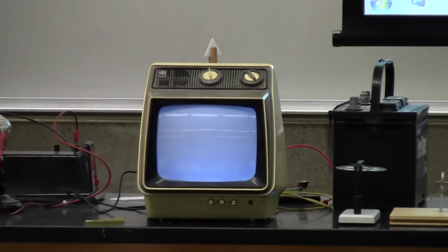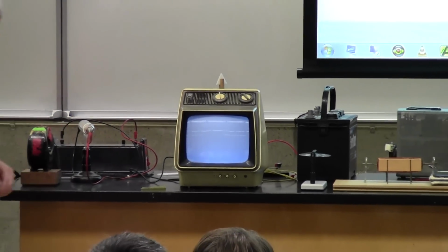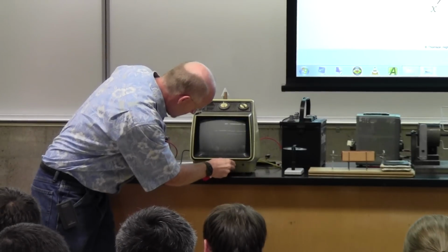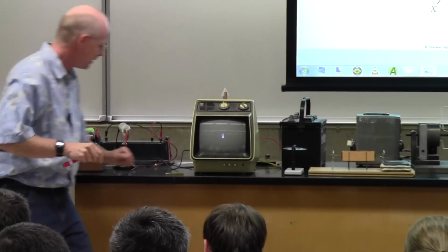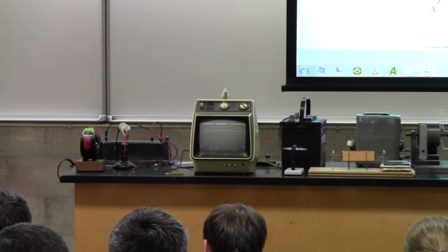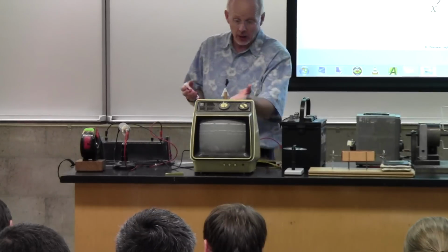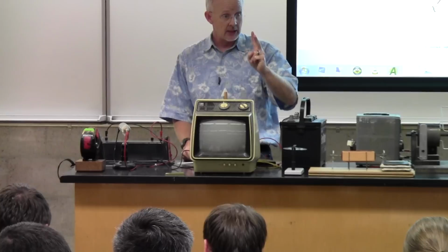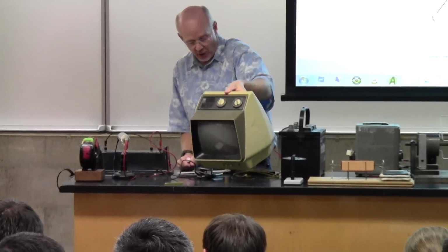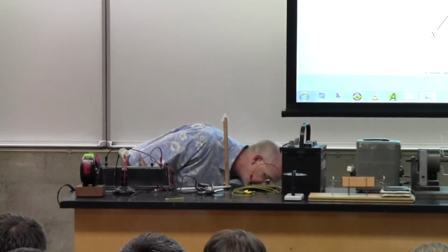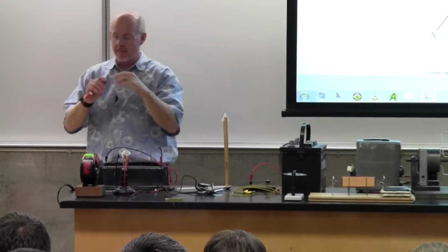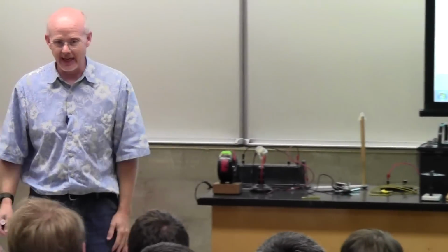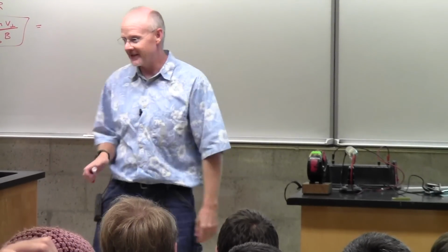And so there's the design of it. Which, by the way, if you're wondering why I use the black and white TV, which aren't easy to find, it's because a color TV actually does this 3 times. It's got one beam for your red, one beam for your green, and one beam for your blue. And in order to separate the red, green, and blue on the screen, there's a metal wire mesh in there. When you bring a magnet near it, that metal mesh can get magnetized. And then when you pull it away, it's still magnetized.